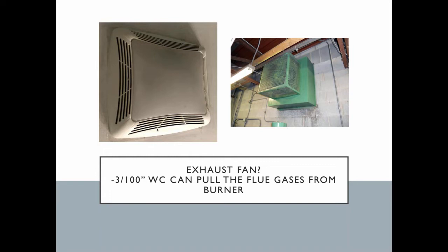We were at one job where they were having carbon monoxide alarms going off, and the person had all of his exhaust fans on because he had 4 kids and they were taking showers, and it pulled the room into a negative condition.